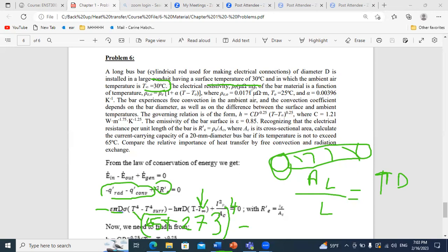But here, because they have the same value, we don't have any confusion. But in case, let's say the surface temperature was, for example, 28, then you will use 28 here in the radiation term. So minus 30 plus 273 to the power 4. And of course, you multiply the result by epsilon pi d sigma. You then get the value of the radiation flux. Minus how to compute h, the convective coefficient, computed from the following empirical relation. And you have all parameters.